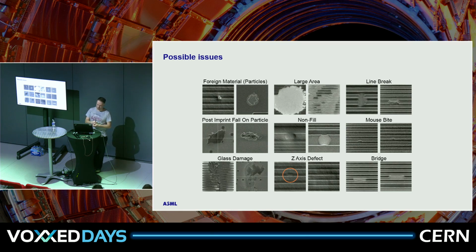And I think there are two main things that we try to detect. One is where you have issues on a particular wafer. Maybe there is a dust particle on the wafer. Then maybe one or a few chips might have issues. That's relatively okay. But if that same dust particle is on the reticle, and we detect it after 1 hour, then basically you have 200 wafers coming through with problems on it. So it's crucial that we detect issues quickly and try to fix them quickly. And as you see here, you can have a lot of different issues.